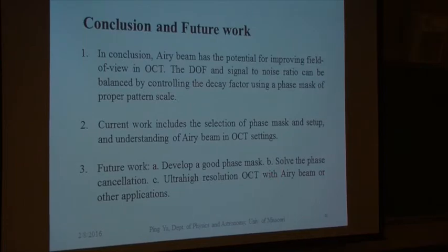I'd like to explain this a little bit more. OCT technology currently is beautifully used for tissue imaging with current resolution. So if you compare current technology by Gaussian beam and Airy beam, there's not too much advantage, although the Airy beam improved depth of field. But after 2 or 3 millimeters, this coherent photon just loses the coherence. Basically, you cannot see anything deeper than that. However, your coherent photon can survive 2 or 3 millimeters.